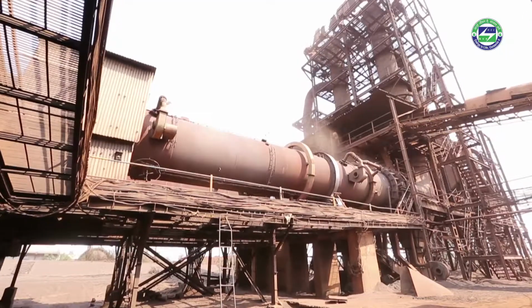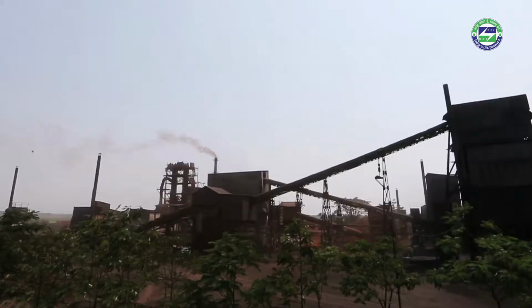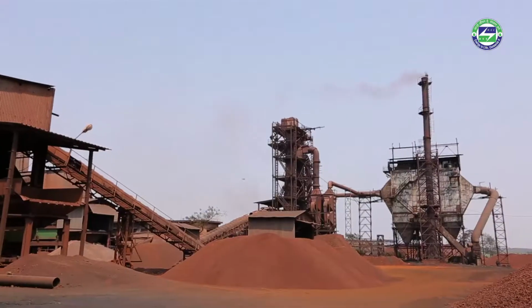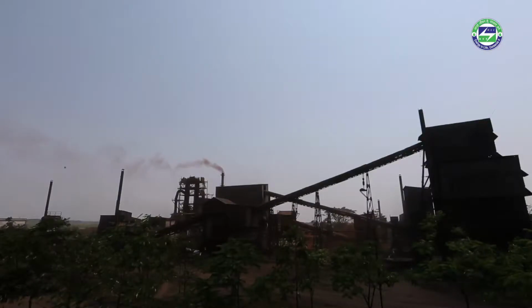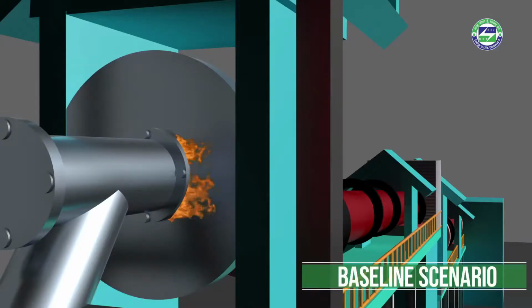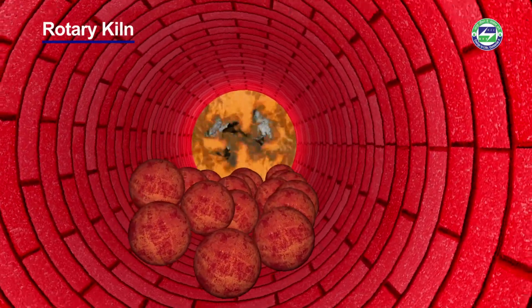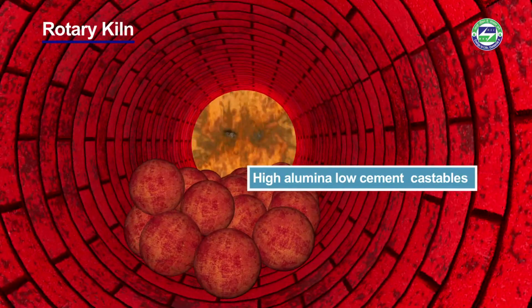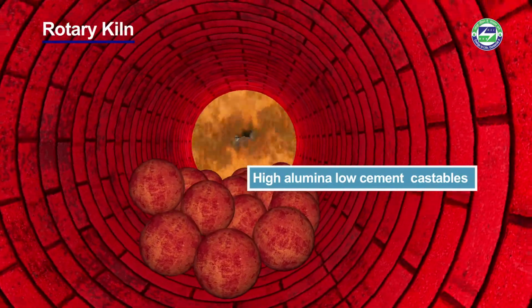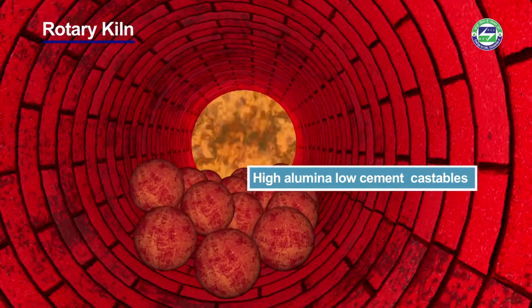The direct reduced iron or the sponge iron sector forms a significant link in the secondary steel sector, supplying close to half of the raw material inputs for the steel melting units. In a typical DRI plant, the rotary kiln is lined with refractory which protects the kiln shell when operated at high temperature. High alumina lining of 6 to 10 inches thickness, depending on the kiln module, is the most commonly found refractory material in the sector.